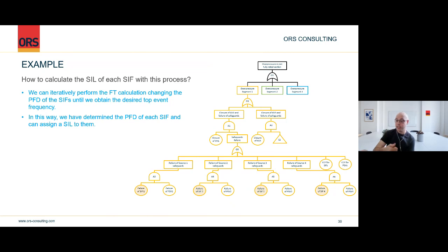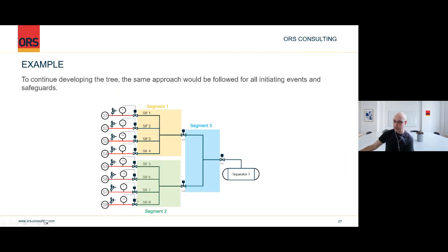It's more detailed. It's going to give you a lot more information as well. It's going to tell you what the easiest path to failure is. So it's going to give you a minimal cut set that is going to say, if this and this fail, you have overpressure. So be careful with those elements. Maybe you want to put more risk reduction in some of these places and not in others. This is a very simplified problem, right?